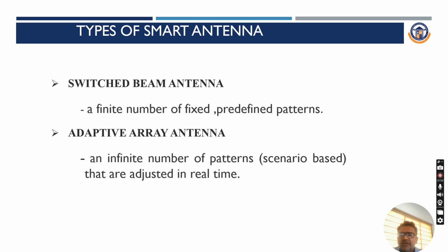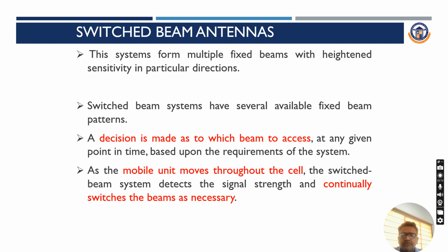In switched beam antenna, there are a finite number of fixed predefined patterns. Actually, it has fixed beams. Adaptive array antenna has an infinite number of patterns, which is scenario based. We can adjust it on a real time basis.